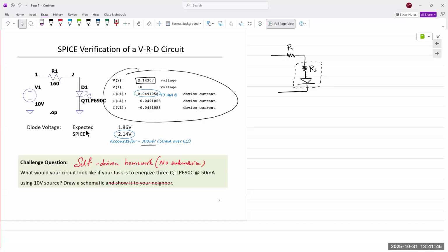LTspice is really good when we want to create a graphical circuit interface. It's really powerful for that. But it has a limitation where it will only allow us to use the models that are available in its library, so we can't really modify any of those models. We'd have to use a SPICE directive.